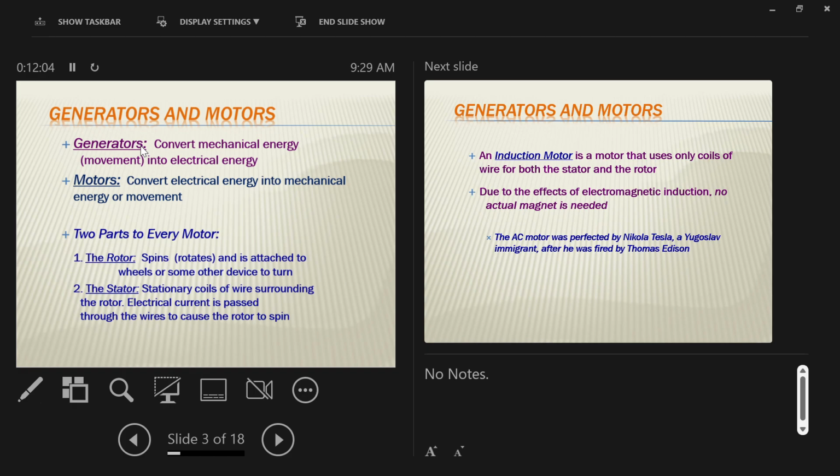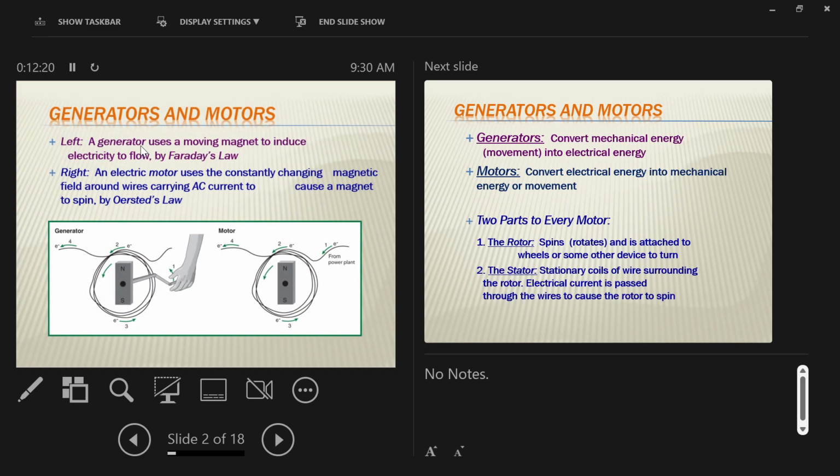Again, it's not perfect. You don't put back everything that you have used, right? But some of the power that you use to propel the car down the road and bring it up to speed is then put back into the battery as you apply the brakes on these vehicles. Really, really smart stuff, right? It's taking a motor, and then using it as a generator when you're stopping. So when you're going, it's a motor, and when you're stopping, it becomes a generator. Really nice little tool. And the idea is simple because a motor is just a generator run backwards. Okay, not literally spun backwards, but the power coming from the wheels and going back through the conducting wires.